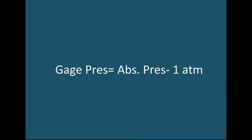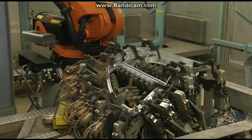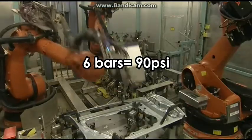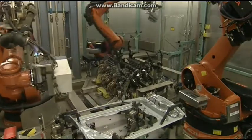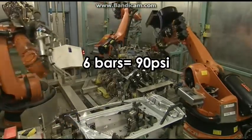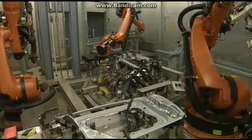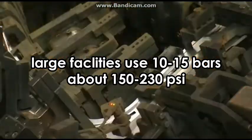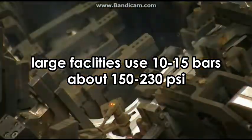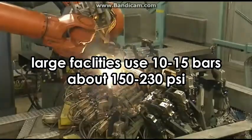Gauge pressure is equal to absolute pressure minus 1 atmosphere. An absolute pressure of 7 bars will read 6 bars on the pressure gauge. 6 bars is about 90 pounds per square inch, which is the average pressure of a pneumatic system. Although in some systems, particularly with large manufacturing facilities, the average pressure is about 10 to 15 bars. This is because, in order to cover long distances, pressure must be elevated to higher levels to ensure constant pressure at the point of use.